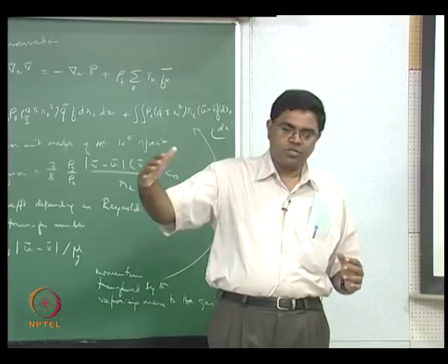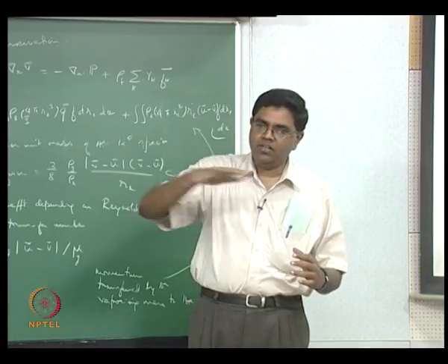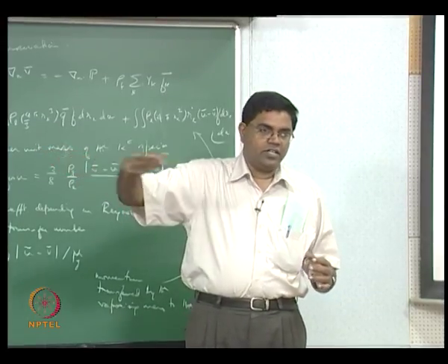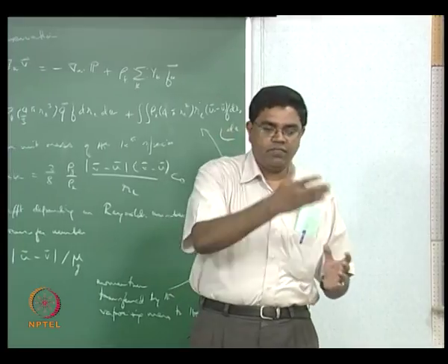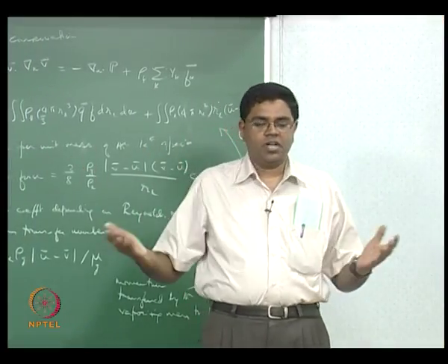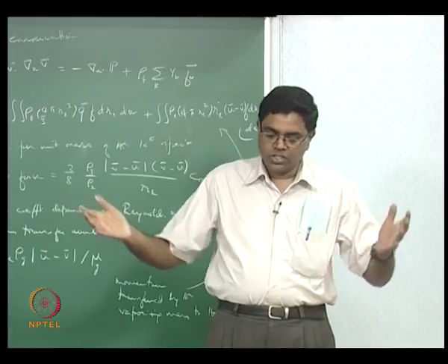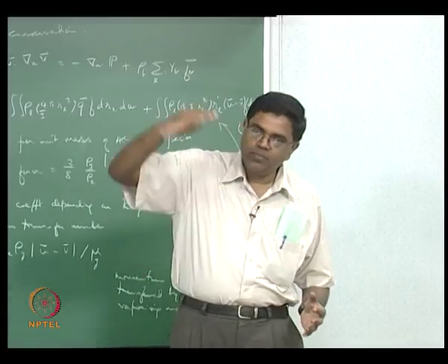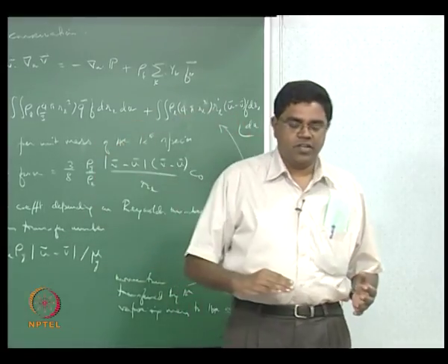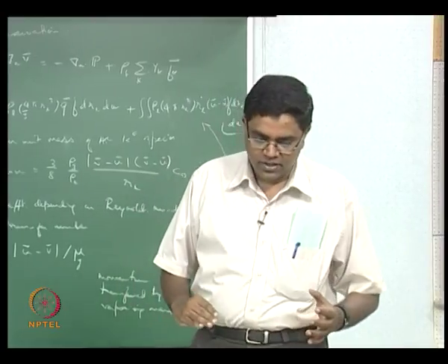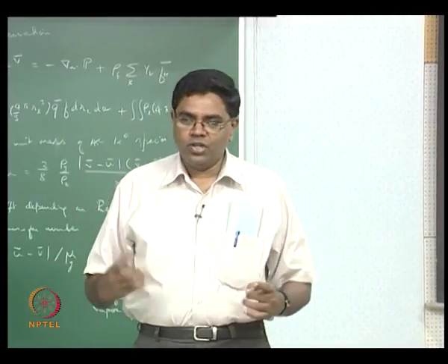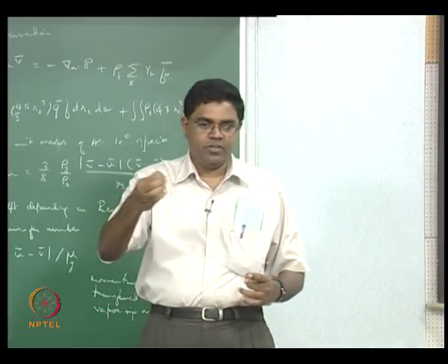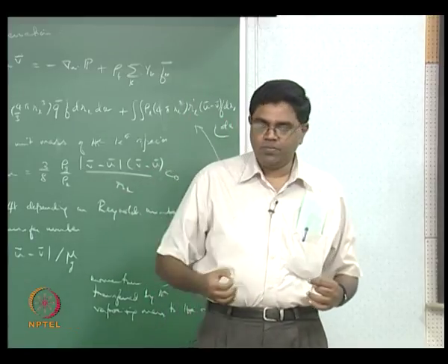So a snapshot, for example, if you were to do something like a PIV of this and take planar data of what the flow field is, you will have large scale motions captured over the larger area with pockets of intense small scale turbulence here and there, because the droplets have just gone past these planes here and there. So that's typically described as a Swiss cheese, because if you take Swiss cheese, you have lots of these holes. There are these holes now filled up with, in this case, the droplet turbulence.